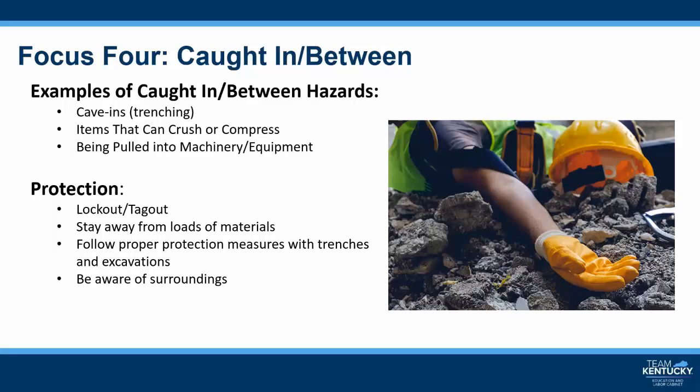There are different ways to protect workers from caught-in-between hazards on a construction site. If a worker is conducting work on machinery or equipment, the best way to stay safe is to ensure that lockout-tagout procedures are in place and are being followed. If material is being loaded, unloaded, or stacked, workers should stay a safe distance from the operation. Flowable materials such as dirt, gravel, and sand should be worked around with caution.